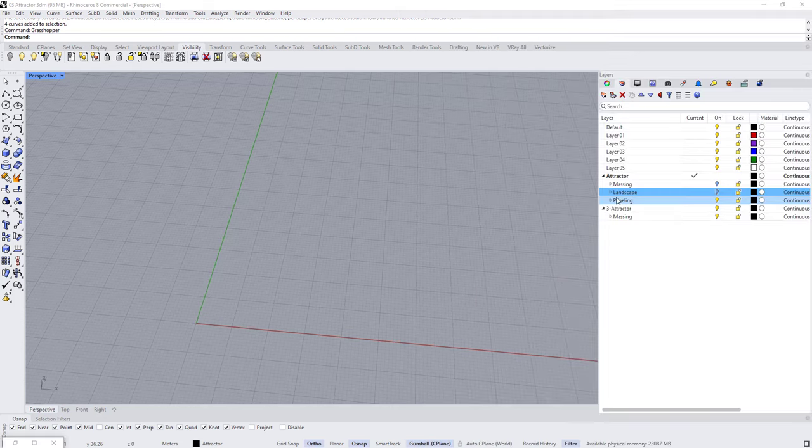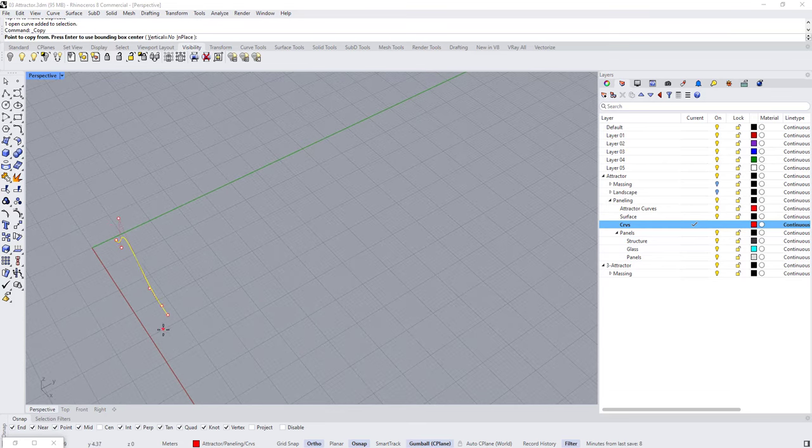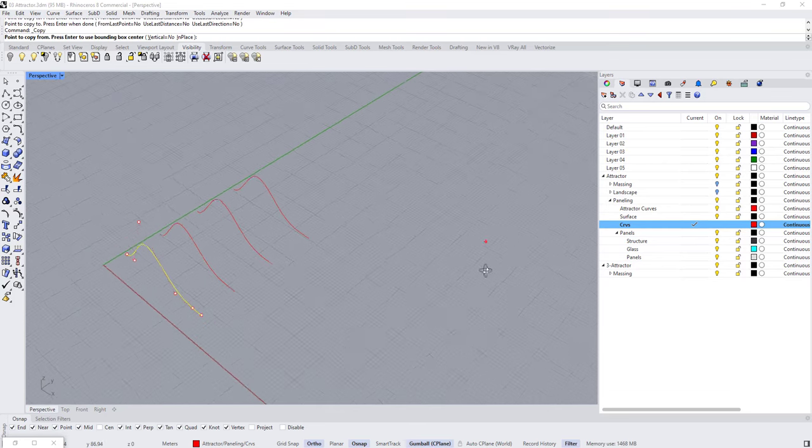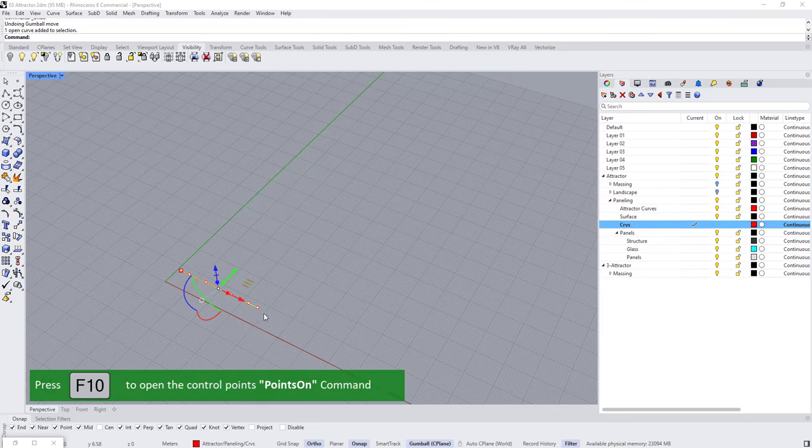And first, I'm going to create a reference surface. So I'm going to create a new layer and let's name it CRV for the curve, reference for the curve. And I'm going to draw maybe a polyline here with a length of 35 meters. I click, select it, I rebuild at 6 control points, and move point like this with a value of maybe 20. Select it, get a copy. 1, 2, 3, maybe 3 copies. You know what? Control Z. Before moving it, I'm going to create a few copies. So get a copy here, here, here, and here maybe.